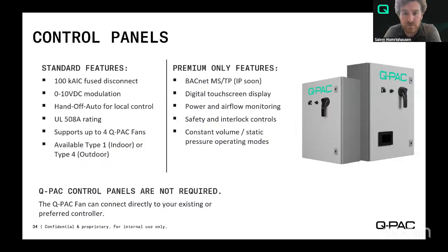The controls cable is going to be run from wherever your BACnet point is, and you're just sending it a 0 to 10 speed signal to run off of, and you can potentially get your ECM plug fan status, your individual airflow, and your multi-motor plenum fan level airflow from that Modbus connection.